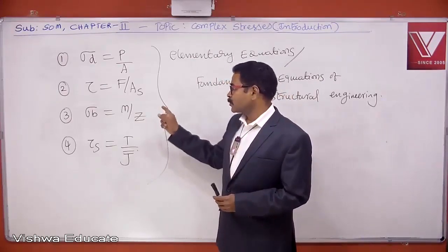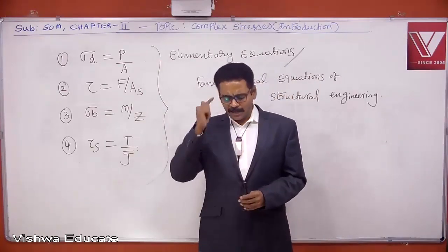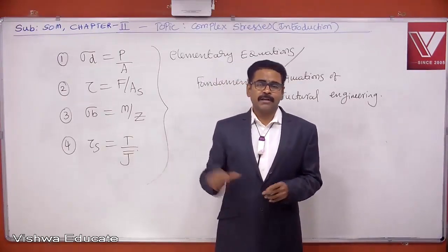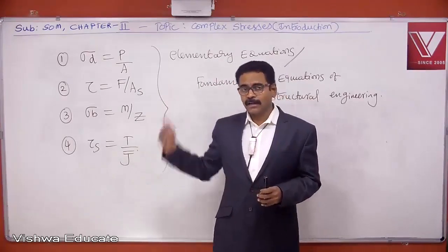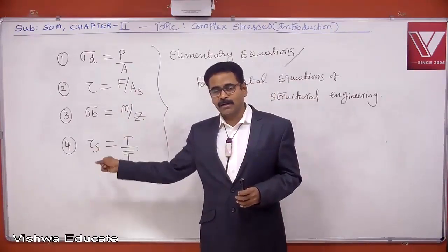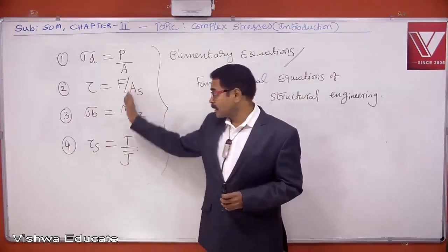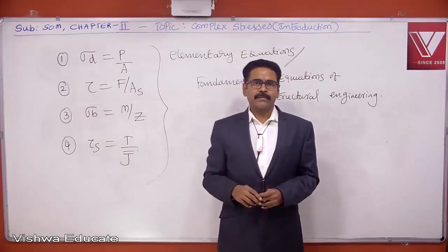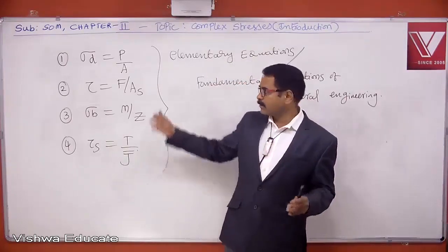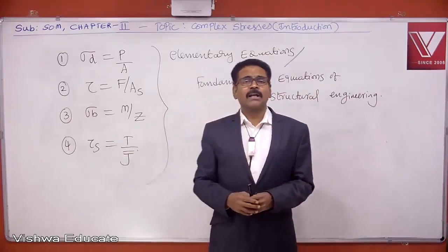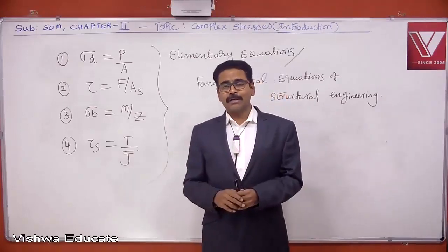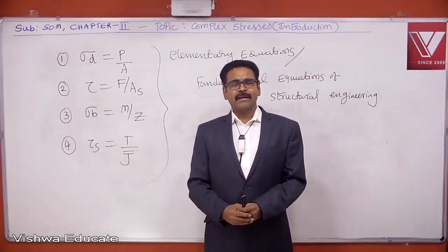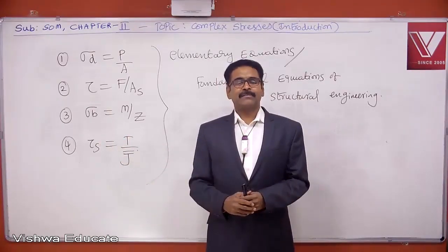If you design any structure by using these four formulae, indirectly, unknowingly, you are making one assumption. What is that assumption? In case of failure, failure occurs about either cross-sectional plane or surface plane, because these four formulae are giving stress on only cross-section and surface. So, that is the unknowing assumption: the structure may fail about either cross-sectional plane or surface plane.